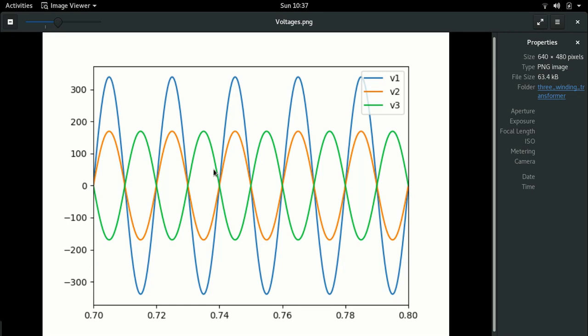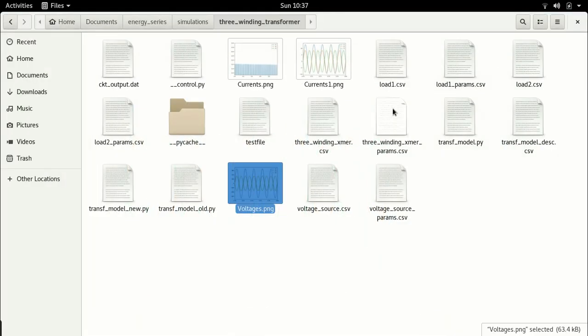However, for the sake of simulation, I will not be going to those frequencies, because in order to simulate at that frequency, I will need to reduce the integration time step of the simulation, which will only prolong the simulation. So for the sake of this lecture series, I'm going to take the switching frequency as 1000 Hz. But just for your information, the switching frequency is never usually this low. It is usually in the range of around 20 to 50 kHz, that is 20,000 to 50,000 Hz. So let me get back to the lecture.